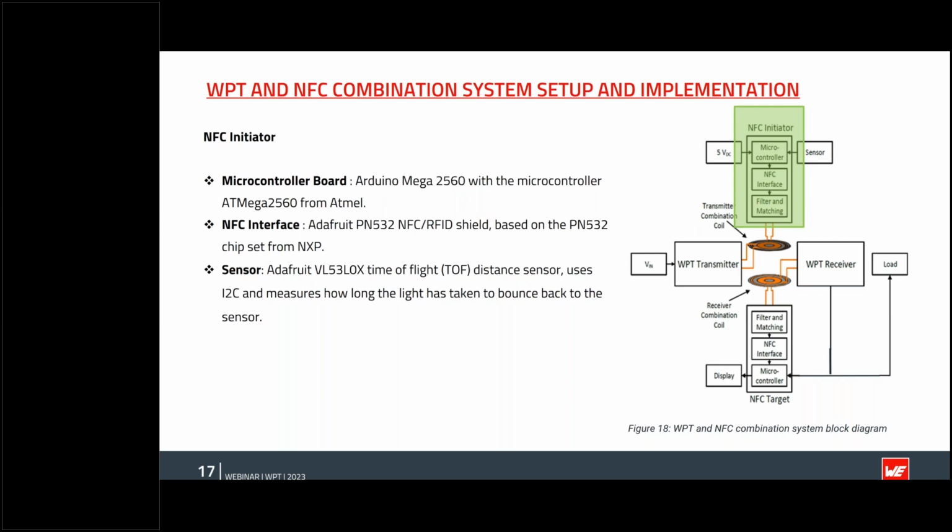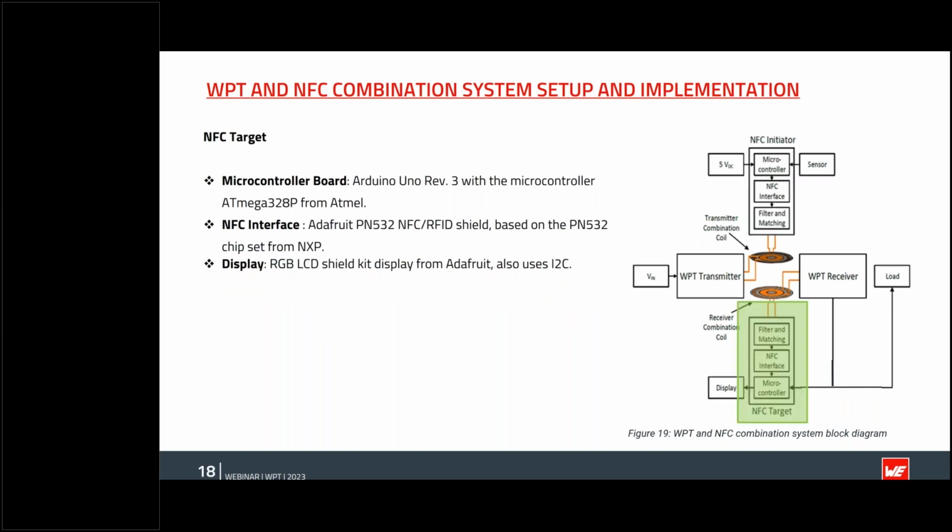Then we take a look at the NFC target. The NFC target has almost the similar configuration as the NFC initiator, but the only difference is that the microcontroller board here is the Arduino Uno revision 3, and the NFC interface is similar to the NFC initiator, the same chip, and the display board is from Adafruit, which also uses the I2C communication protocol.